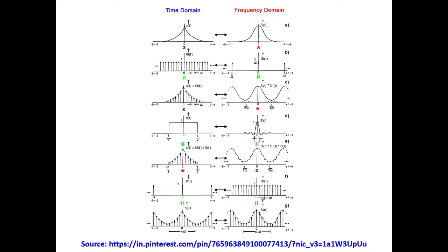What we are doing, okay? Initially, if you remember, when we are sampling the signal in the time domain, I said we band limit the signal. Suppose my sampling frequency for the signal is Fs, then Fs should be greater than or equal to 2Fm. Okay. So Fm is the band limited signal.